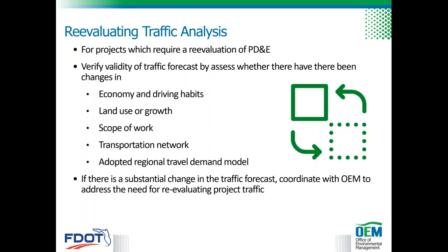So the majority of traffic forecasting and analysis should be completed during the PD&E phase. Once the traffic forecast and analysis is completed, the subsequent phases, which would be design and construction, should use the same traffic data for design and operational purposes, such as designing turn lanes, signal timing, or traffic control plans.